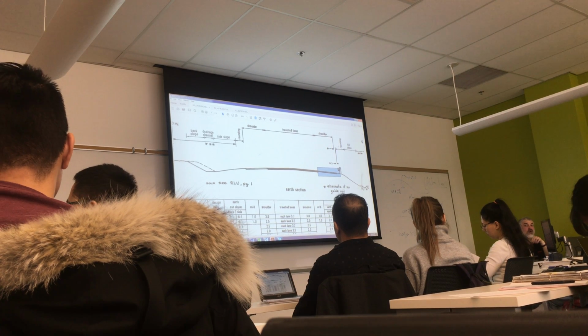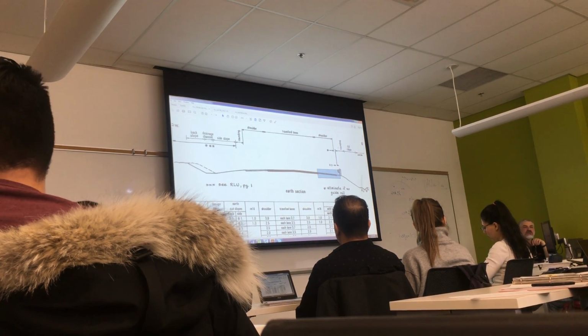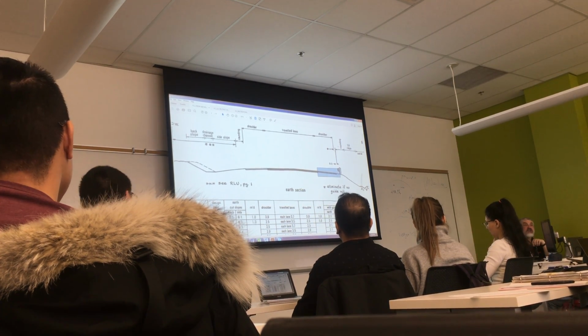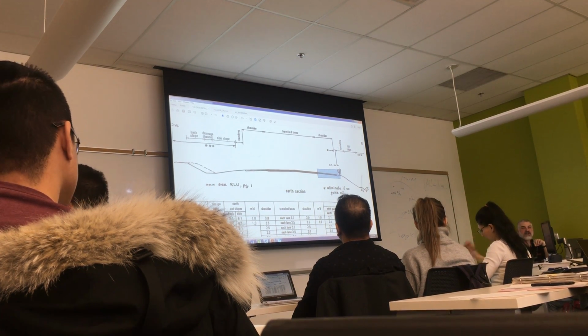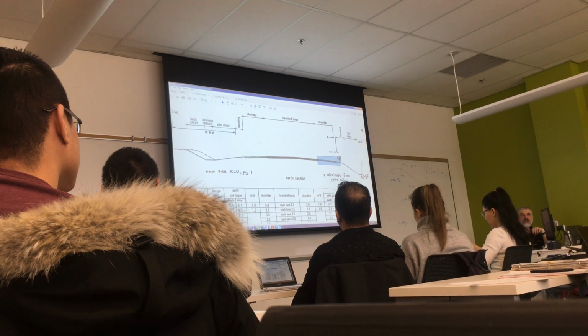Now, if you manage to draw it with the no guide rail slope, if I was able to complete this with a 6-to-1 slope, I'd be done. I wouldn't have to analyze anything. But because I compromised the no guide rail condition slope, now I need to check, do I or do I not need a guide rail? And we'll see the factors that determine that analysis.